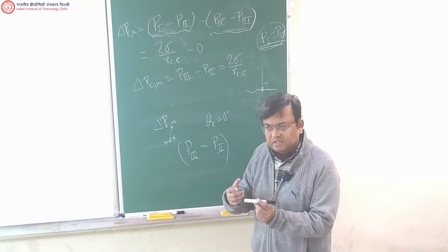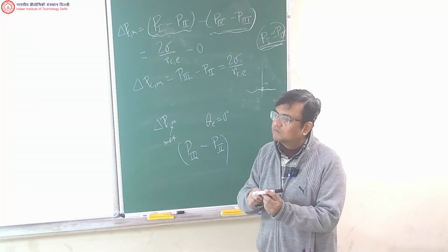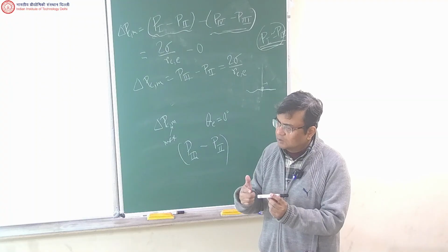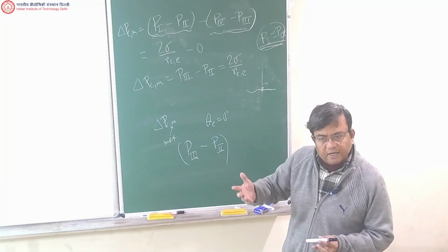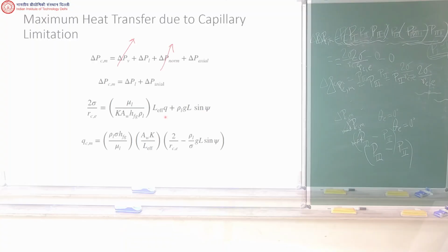Because vapor density is low, you get a very high vapor velocity for a given mass flow rate, and that might choke the flow, with all kinds of effects. So it's not like you make a heat pipe and it will work under all conditions, obviously not.